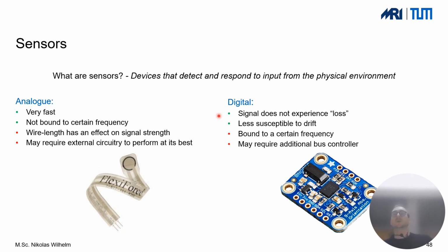And then on the other side, we have the digital sensors. They're quite nice because they already provide you with everything you need. You already get the digital output of your sensor, so you don't need to handle all this conversion and what is actually going on. Often they have internal logic already, and you can look in the data sheet at exactly what the signal will tell you.